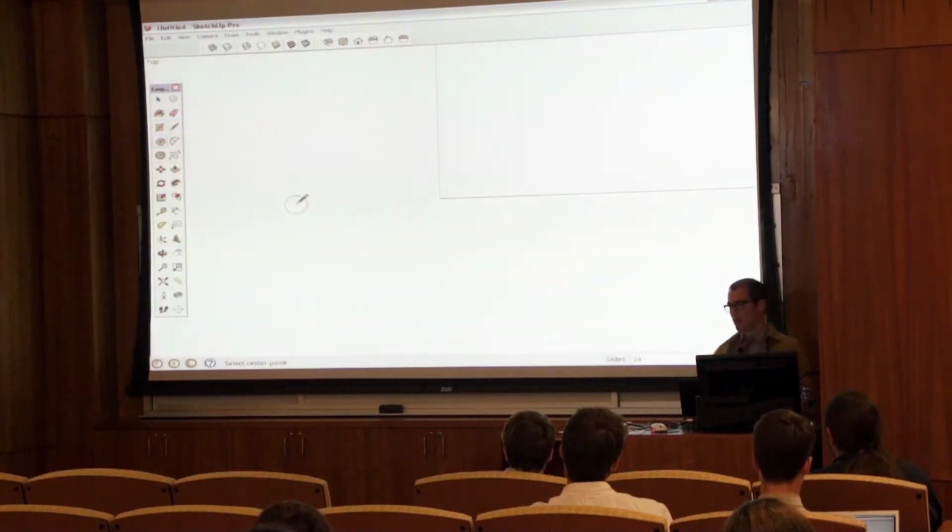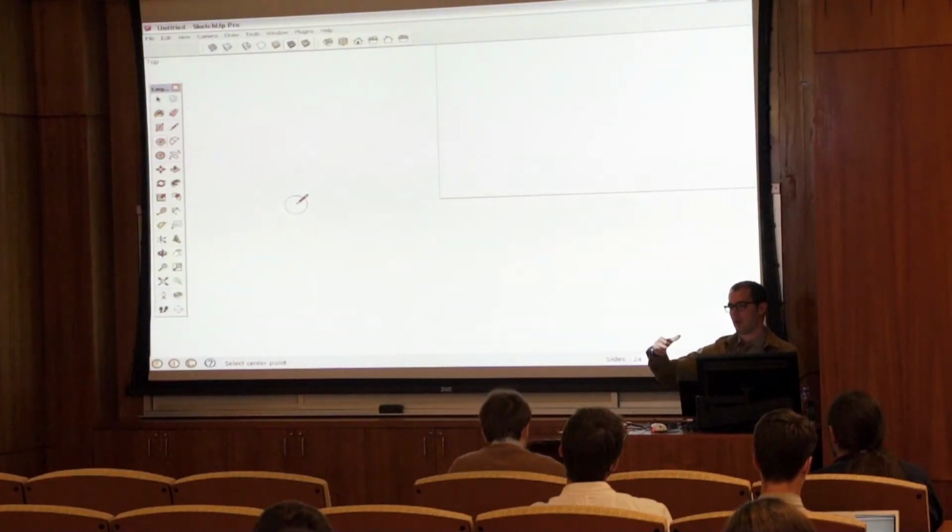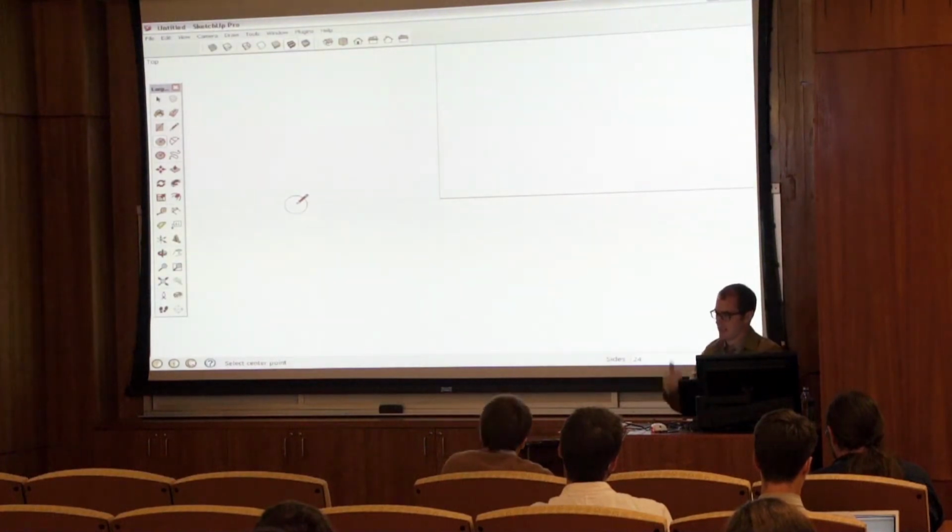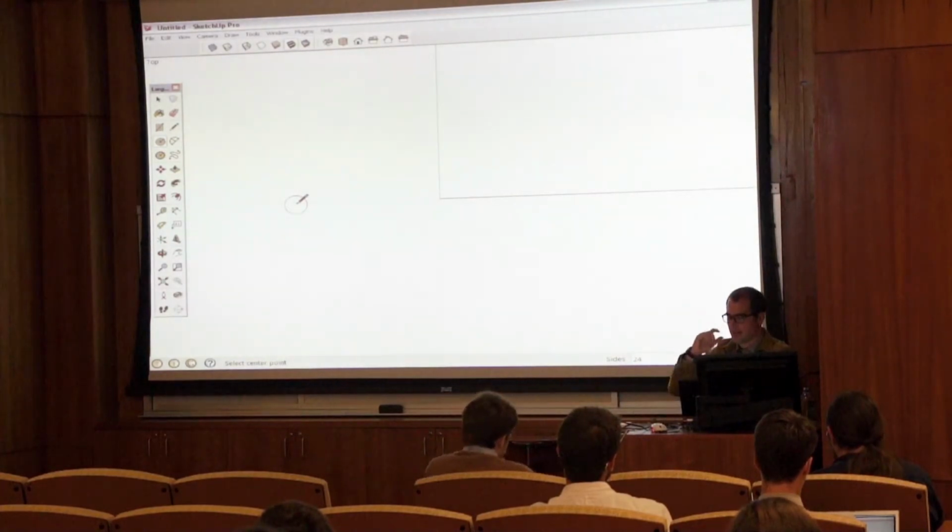One thing to note before you draw with the circle, and if you ever import circles from AutoCAD into SketchUp: SketchUp doesn't create true curves. It's a limitation of the program and of the software. What it does, though, is create them in segments. So by default, the number of segments is 24.